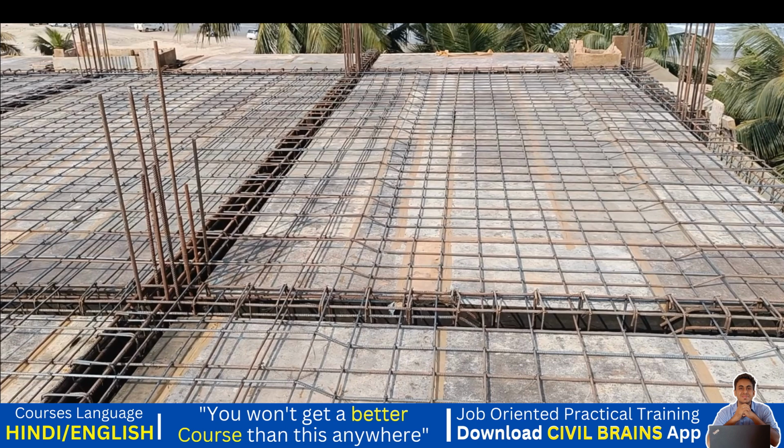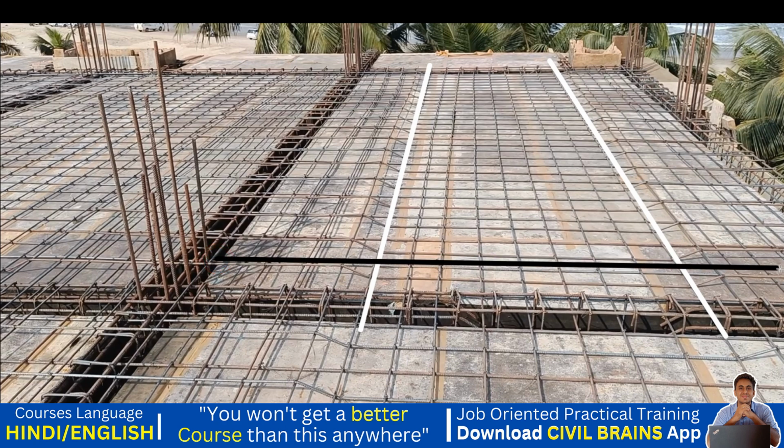One more point I want to clear. Since the bending moment itself is less near the support, I'll put one line. This was my cutoff point and this was my cutoff point. After this point my bending moment was very less, after this point also very less, right? So I gave one bar straight, starting from here, and after that I gave another bar straight.